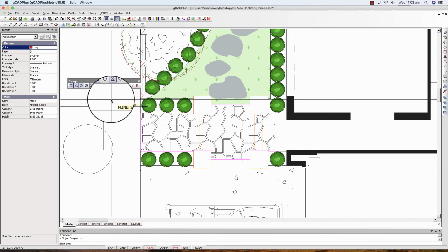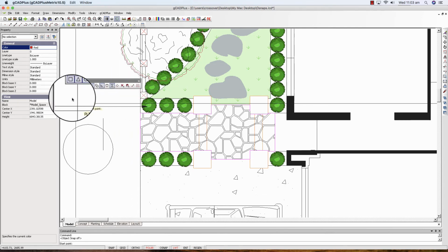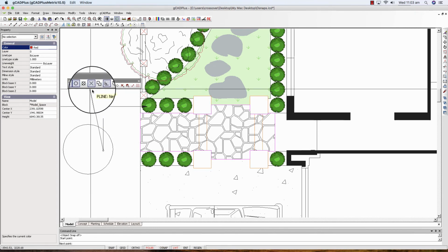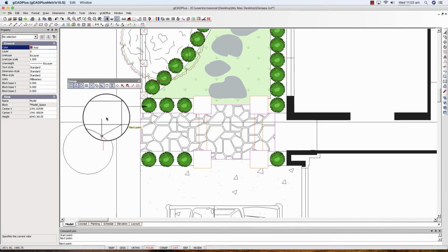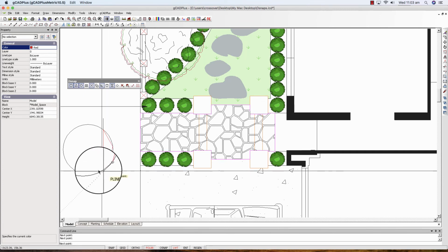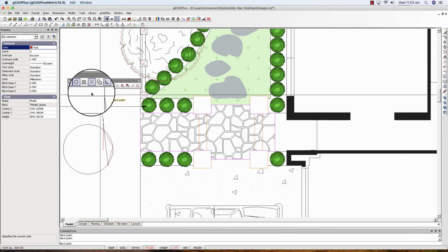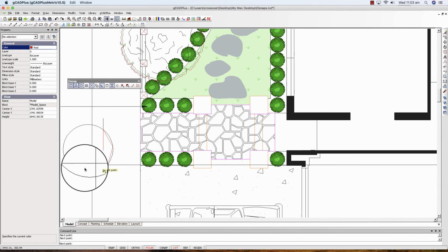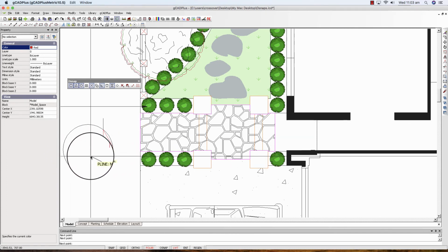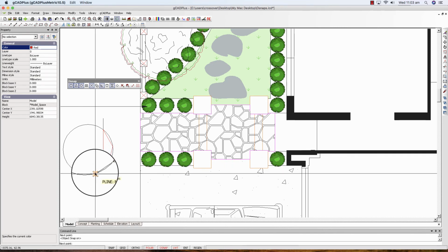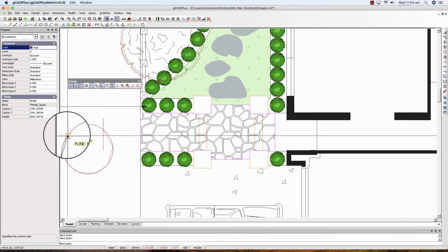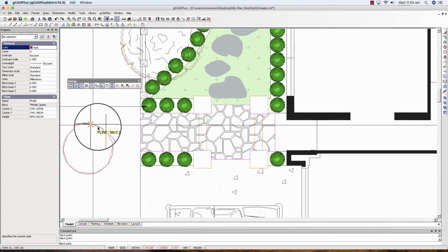What I will do is just come, I'll try here, click on that one, and now it finds it. Now I want intersection, and it finds an intersection. Now I want nearest, near, near. And what I want, notice I want a whole series of nearest, and so I need the Osnaps back on. So F3 again, and we can go nearest, nearest. If I make them quite close together, we'll get the sort of shape that I'm after.